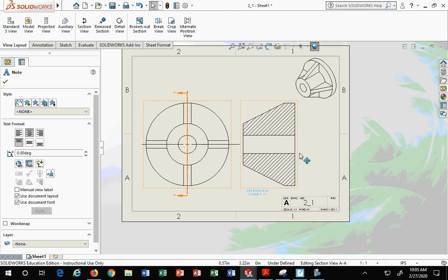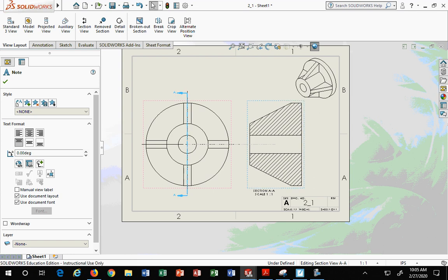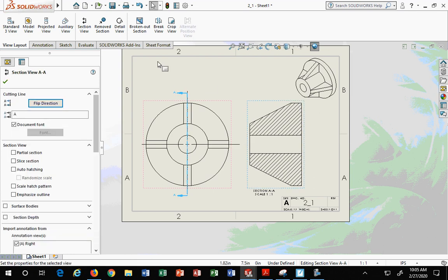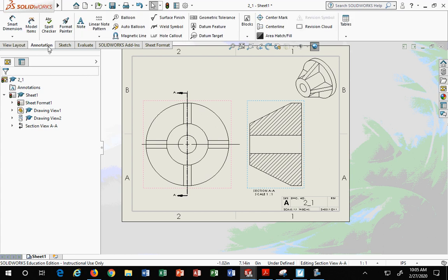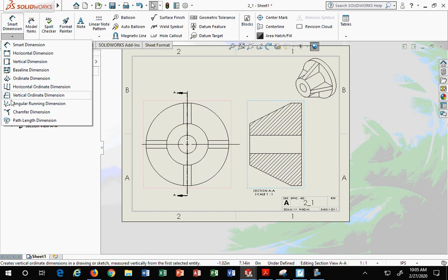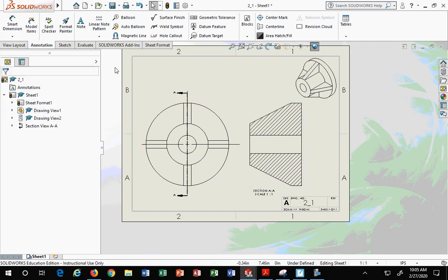The things that are missing are your dimensions. They need to get added into this. But your teacher's lazy. So how do you do that without a lot of work? You go over to the tab called annotation, and you have two dimension choices. I know you're going to gravitate, like everybody else does, to smart dimension and start manually dimensioning it. All right, you've taken a Ferrari, taken out its engine, took off the tires, and now you're running it like AutoCAD. Stop doing it.